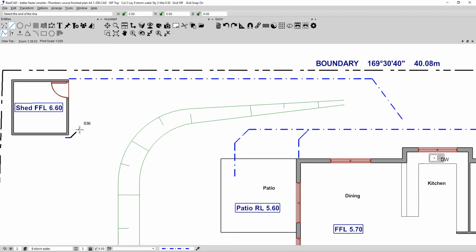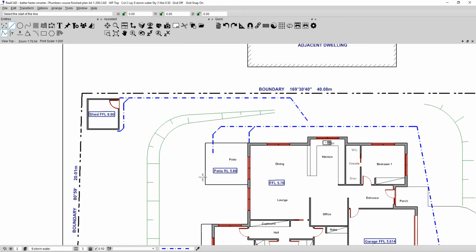For appearance, I'm going to come out here one step, and then I'm going to draw it up in this direction, and again get to about 2400. That's fine. Come up at 45 degrees, and again I don't have a diamond showing, so I'm safe to click, and I'm very happy that that is where the pipe runs.